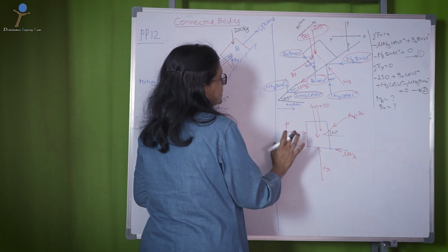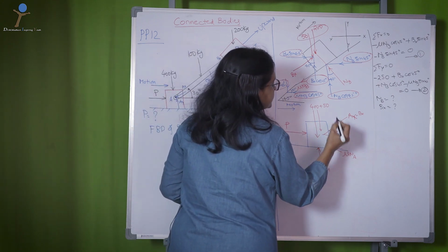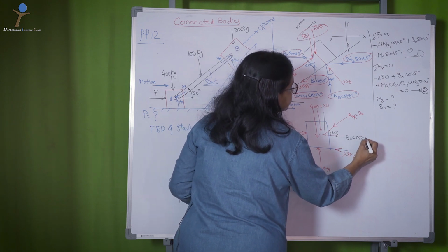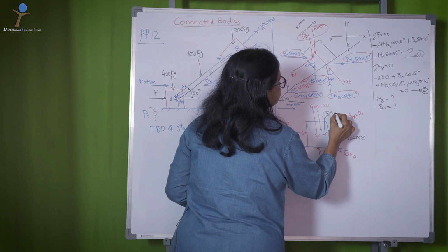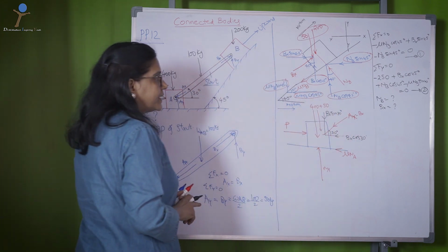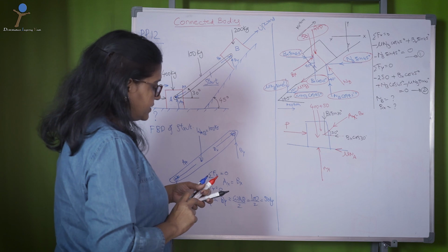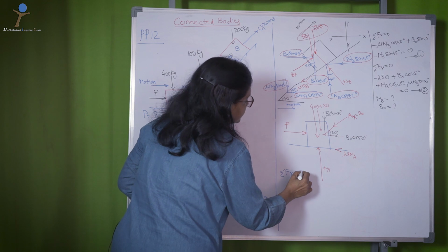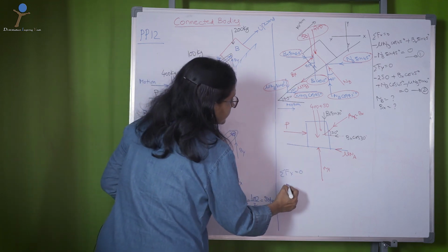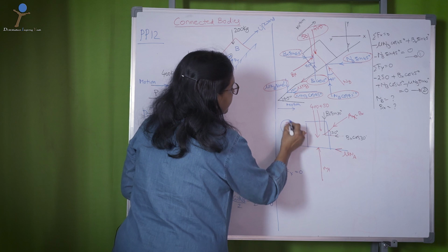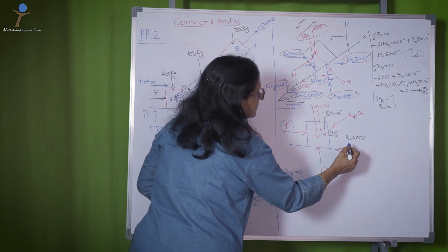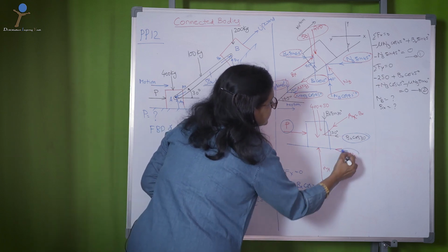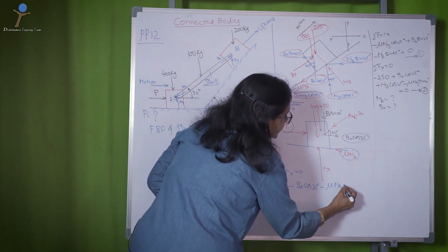This is a very simple system of forces. So, you just resolve this into horizontal Bx cos 30 and Bx sin 30. Then apply the forces here as sigma Fx equal to 0: plus P minus Bx cos 30 minus mu NA equal to 0.